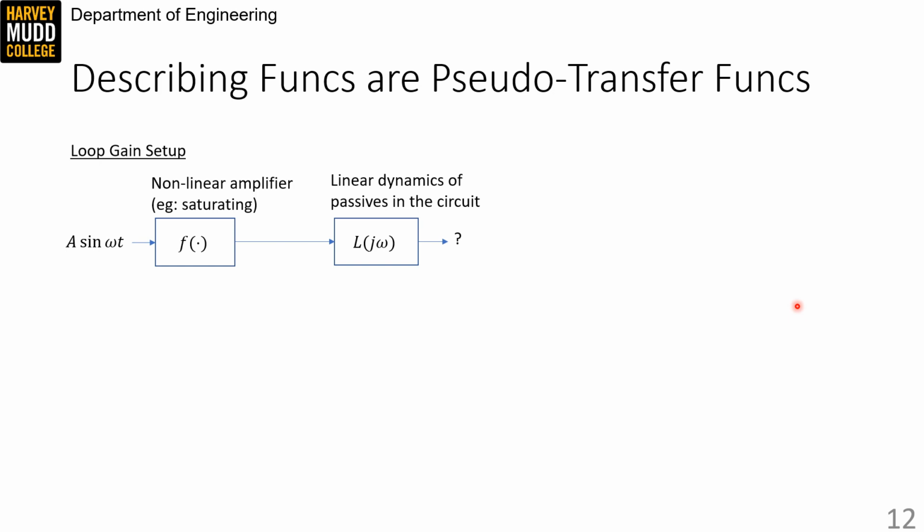So when we make oscillators, what we see is they start themselves up, grow to a large amplitude, and then self-sustain, which is different than a purely linear system. That behavior can be tracked back to nonlinearities in the amplification elements that we use. Any amplifier we build has its gain change when the output approaches the rails, and that looks like a nonlinearity.